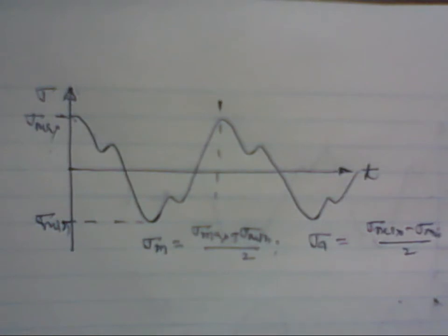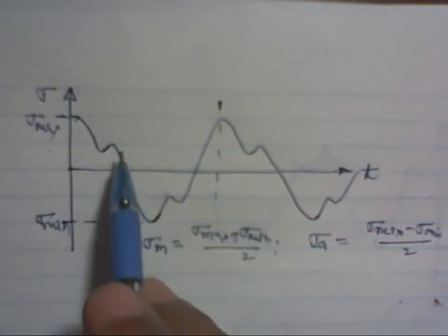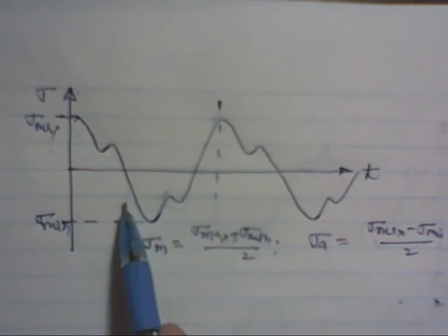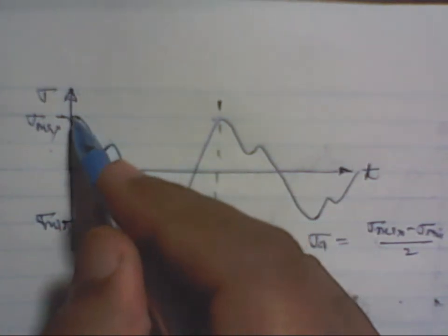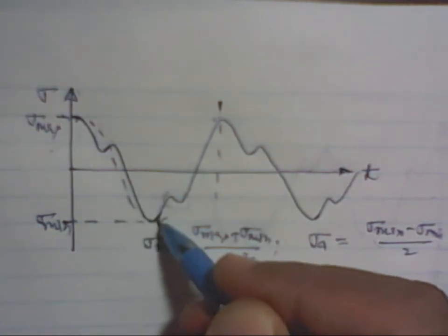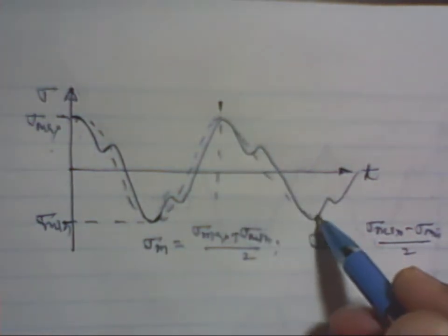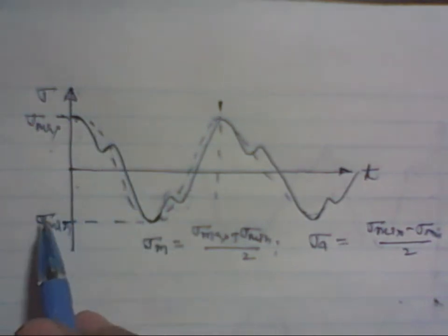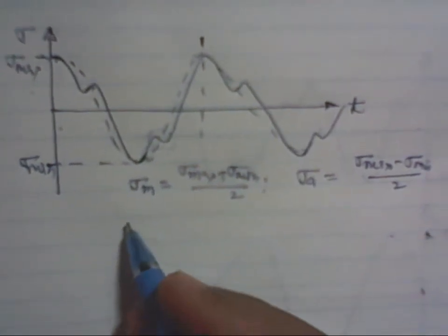Another important fact is that we are not bothered what is happening within the cycle. If we see from this to this, one cycle, stress is varying here, stress is again fluctuating here. But for designing, we are interested in the maximum and minimum value. So from now onward, we will represent the stress by a simple sinusoidal wave, just to represent the maximum value and minimum value, and we are not bothered how it is varying if some change is also taking place within the cycle. Now there are a few more parameters that need to be defined for further analysis.